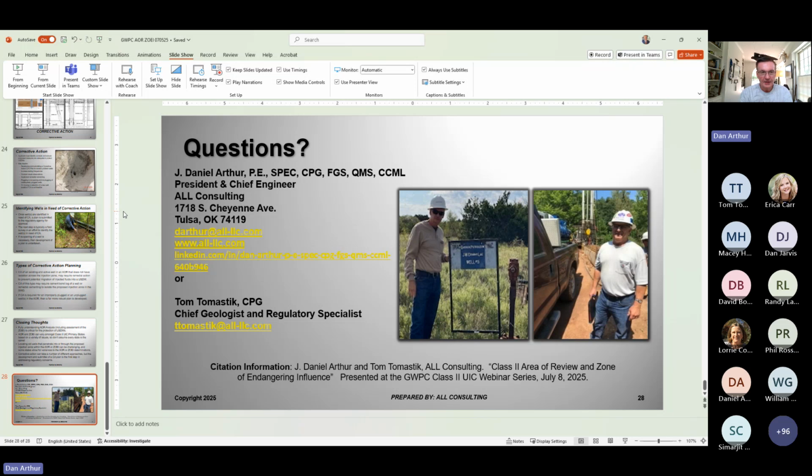You know, I talked about this from a base perspective with ZOE and all that. Others have used various types of models. So if you're in an area where the geology is very different, or it's stratified, or a hundred other zillion things, you may need to get a model done and utilize that, because just the base calculations are inadequate. But you need to do your research up front to really understand that geology.